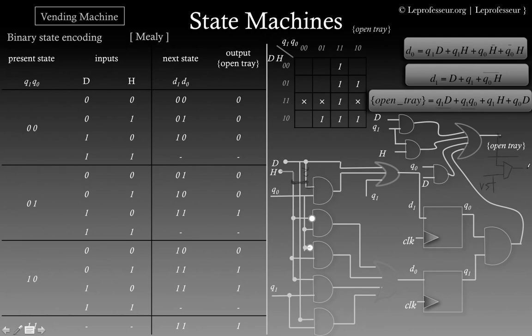If you're gonna use it as a feedback path, it must have to be synchronized, or if you're gonna use that output in some other blocks which are working on a different clock domain, it must have to be synchronized. Okay, so that's a variant of Mealy machine and Moore machine for this small vending machine example.